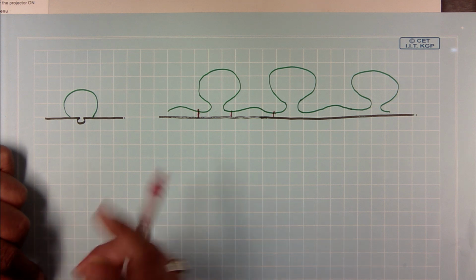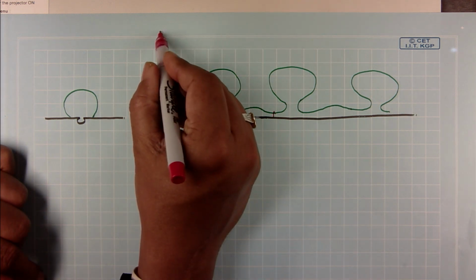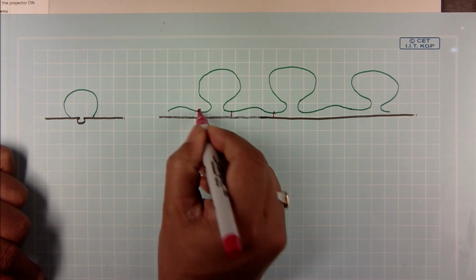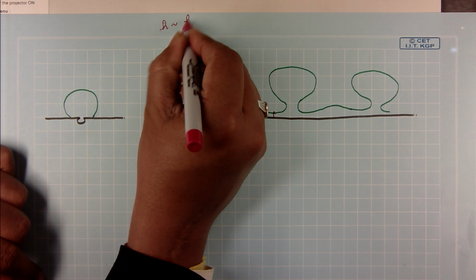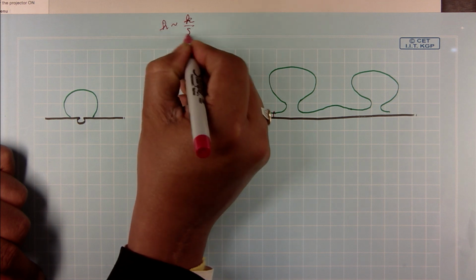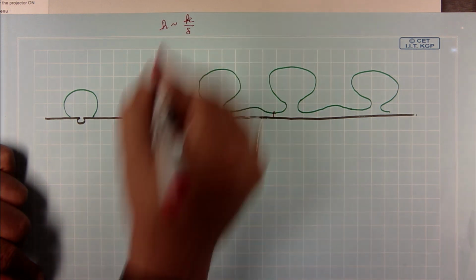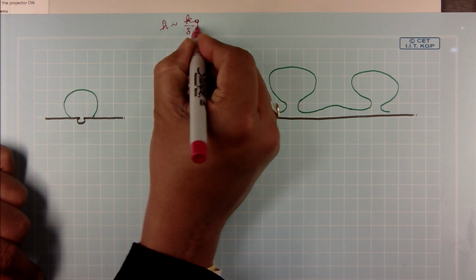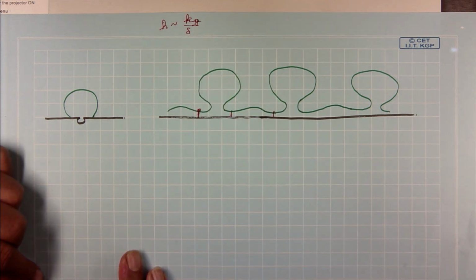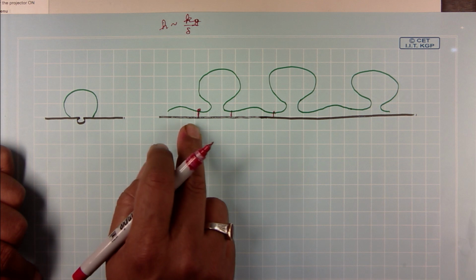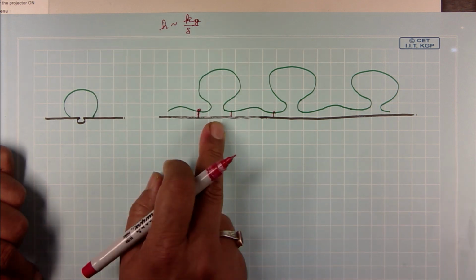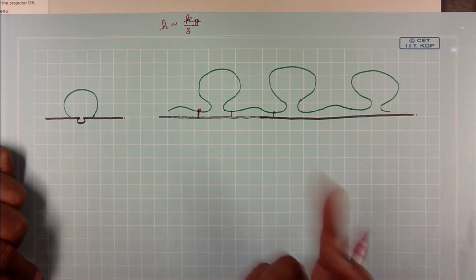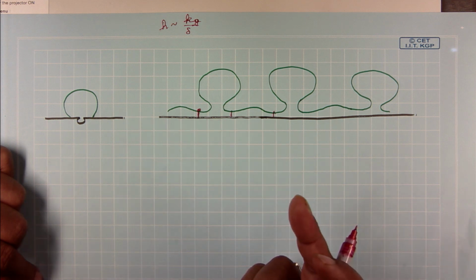In other words, the heat transfer coefficient at any location is proportional to k_g by delta, the k of the vapor divided by delta. So, wherever delta is small, your heat transfer coefficient is high, wherever your bubble is thick, the heat transfer coefficient is small, is not it?